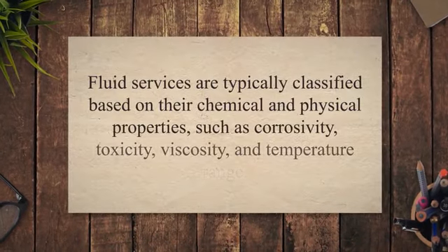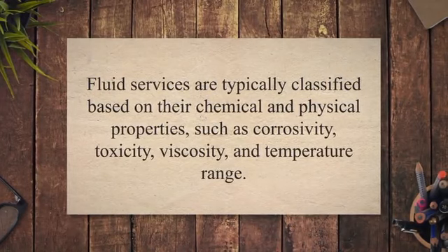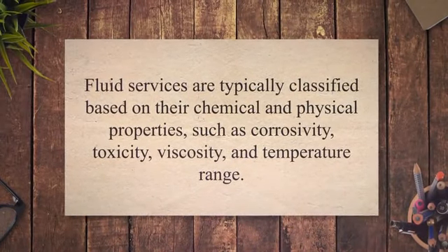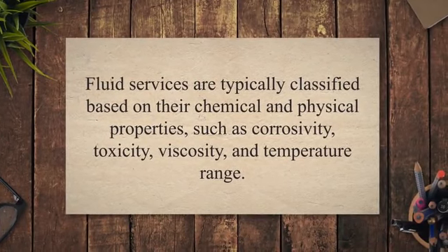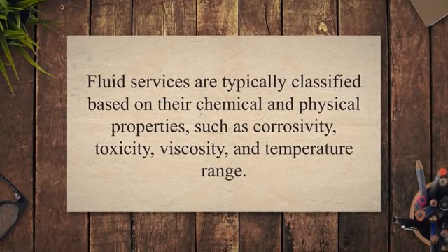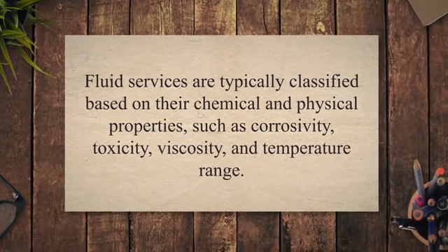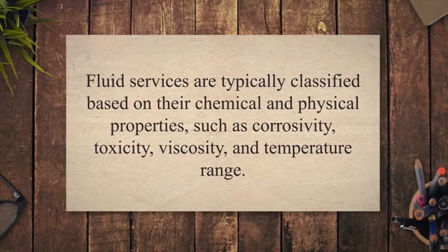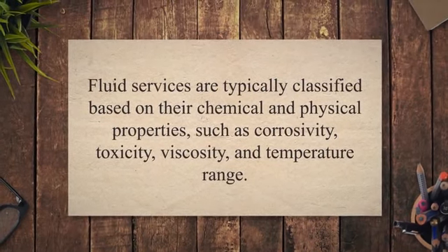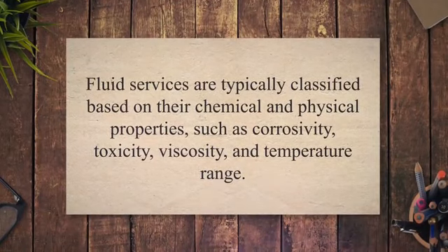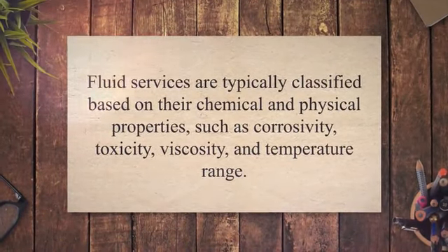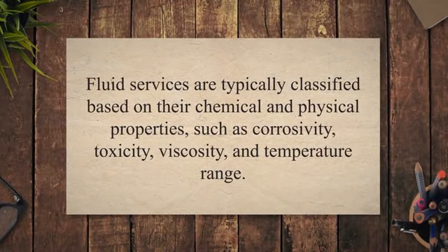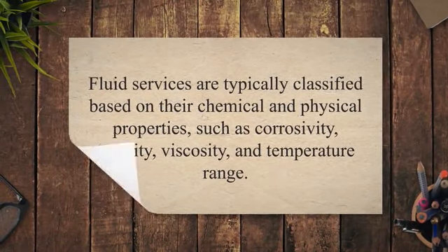Fluid services are typically classified based on their chemical and physical properties, such as corrosivity, toxicity, viscosity, and temperature range. Various fluids like water, steam, oil, gas, acids, bases, and solvents fall into any one of the fluid service categories. The appropriate piping material and construction method will depend on the specific requirements of the fluid service.